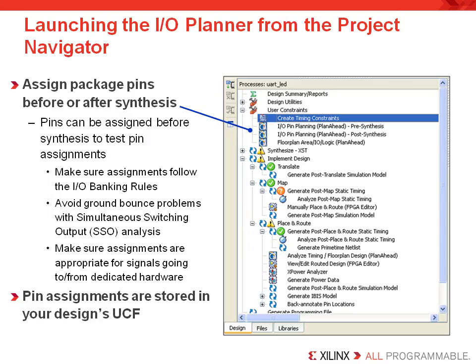The I/O Planner is the pin assignment editor for the ISE and the PlanAhead software. PlanAhead also has design analysis and floor planning functionality, but we're going to limit our discussions to just the I/O Planner for now. If you'd like to learn more about PlanAhead, we offer a course on all of its functionality. To start the I/O Planner, you click on the pin planning option before or after synthesis as shown in the Processes window. Generally, designers are planning their pins even before synthesis to ensure their board layout is effective, and of course the performance is not negatively impacted by making poor pin assignments.